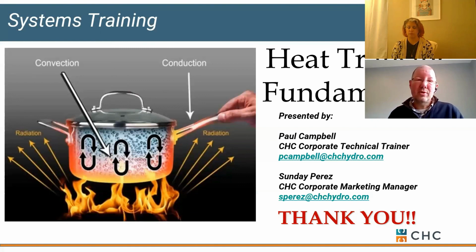Chemicals get tricky, and that's certainly not my strength. If your chemicals aren't a good balance, you may be attacking your gaskets. Honestly, if your gaskets fail or they have to be replaced, if you're replacing the whole gasket set, a lot of times it's cheaper just to buy a new heat exchanger, unfortunately.